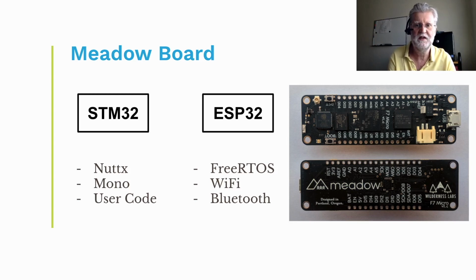The second is it gives more power to your application. So the STM32 can be running your application when a Wi-Fi request is made. This is offloaded onto the ESP32. The STM32 can then return to running other tasks within your application until the Wi-Fi request is completed, at which point the ESP32 would signal that a response is ready and will be passed back to your application.